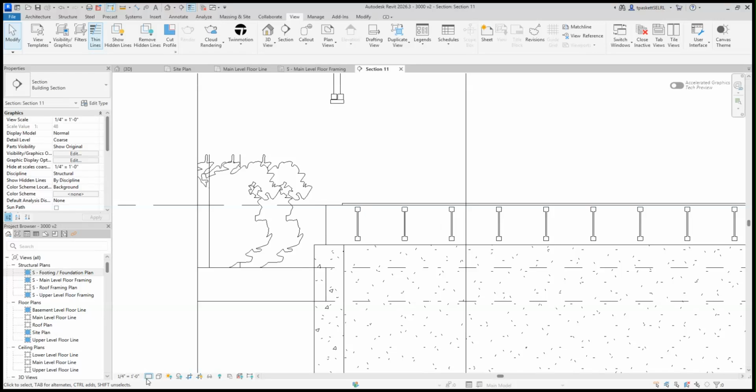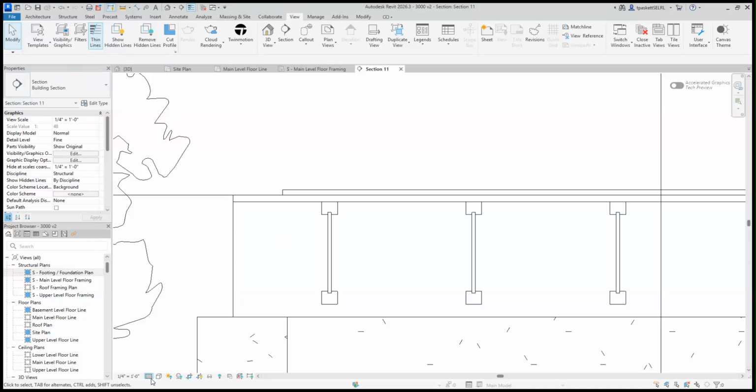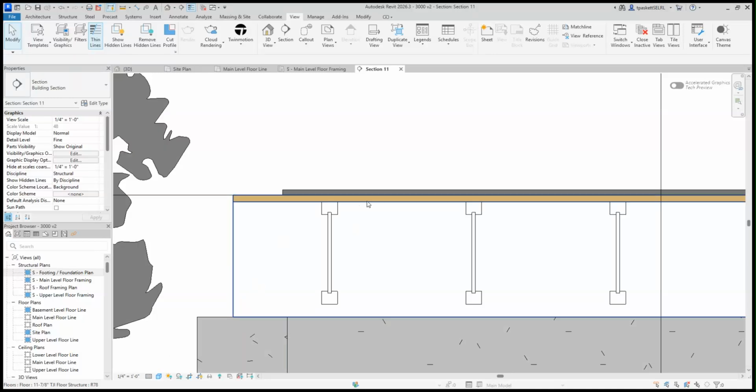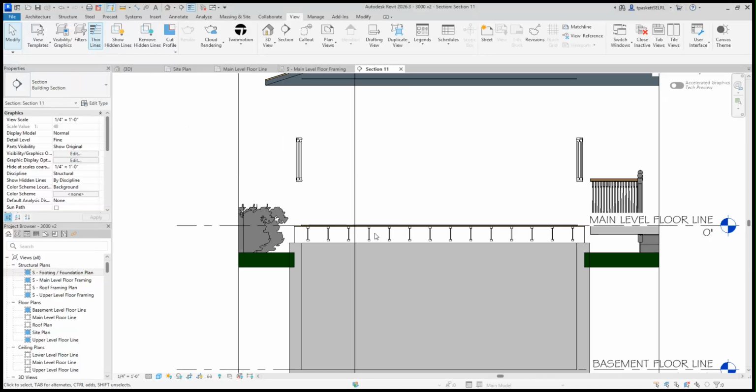But if you put the detail view onto fine, you'll now see that we're below the subfloor. If I put some color to it, it's a little easier for you to see. So there's the plywood, and the floor joists sit right underneath that. Really important you get those placed right, or they show coming up through your carpeting.